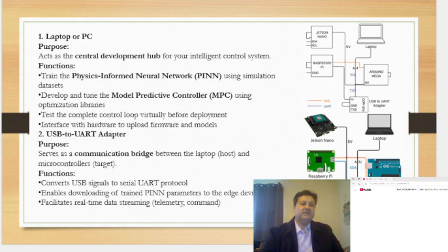So here it is. Now Arduino Mega pin A4. If you see here, there is a pin A4, SCL, I2C serial clock, connected to the Pi and Jetson bus. This one is connected to Arduino Mega and this Raspberry Pi, right? This is connected here.